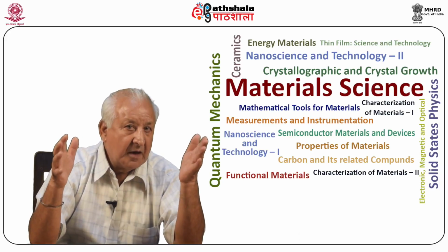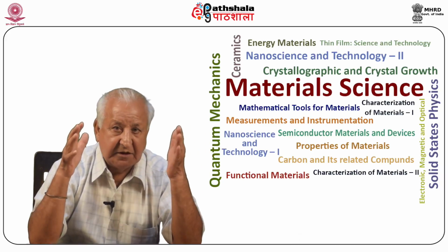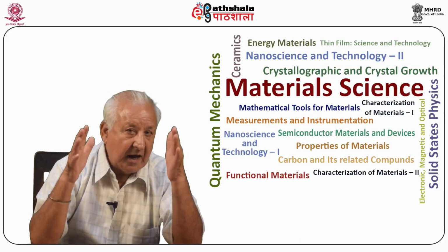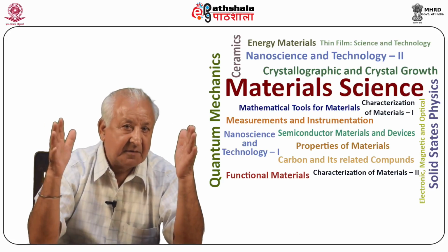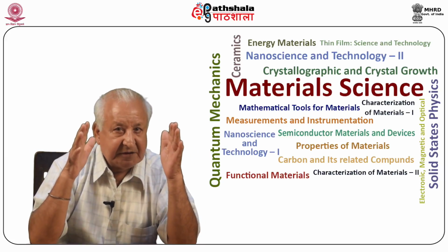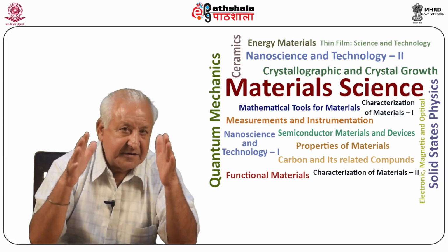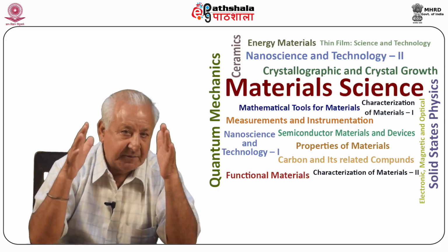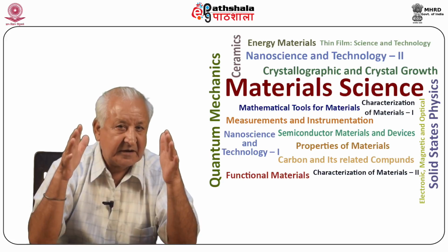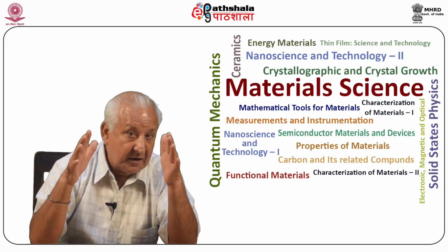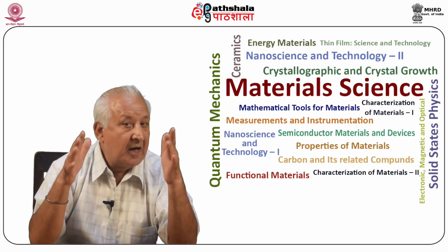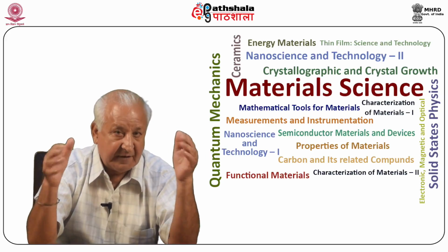The material to be grown and the encapsulant are placed in the crucible, which is heated by an RF field. The encapsulant melts first, and a layer of encapsulant separates the melt from the crucible as illustrated in figure 30.7a. The seed crystal is brought to the melt surface as shown in figure 30.7b. The growth then proceeds as usual, see figure 30.7c, but the crystal is covered by a layer of encapsulant which prevents it from decomposition. The crucible and RF coils are placed in a pressure vessel.